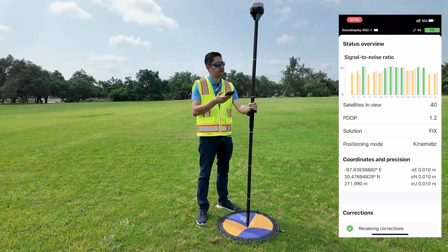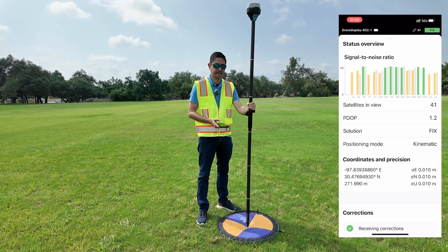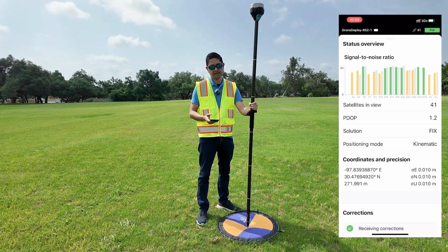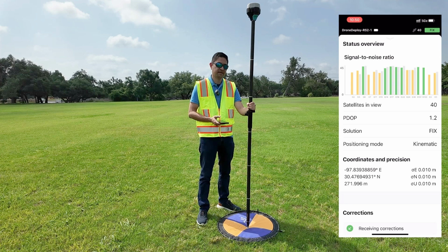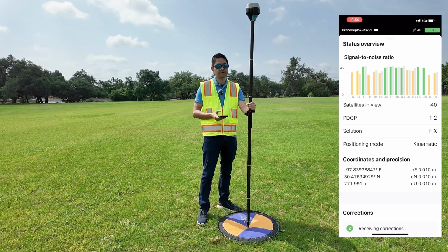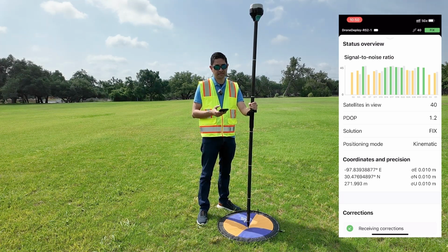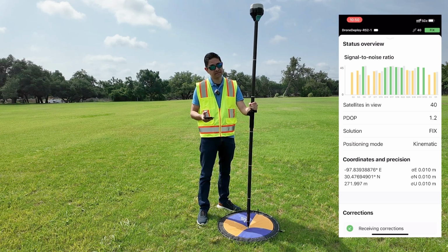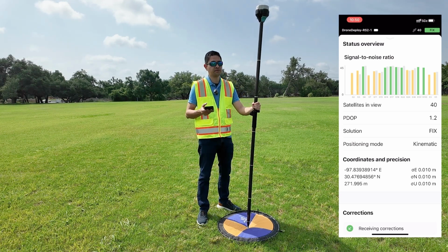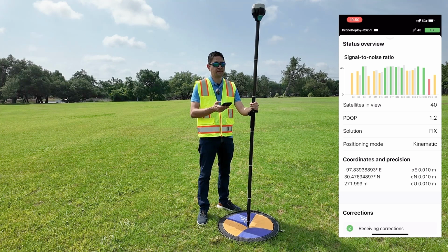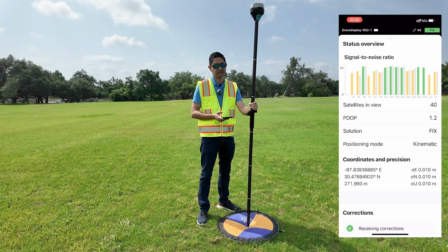So we place the rod on top of the target. The target is a high contrast checkerboard target. The most important thing in your targets is that we need to be able to see the center as precisely as possible. You can spray paint it, but we suggest if you're going to go that route to actually use a stencil that is going to mark or delineate that center as precisely as possible.